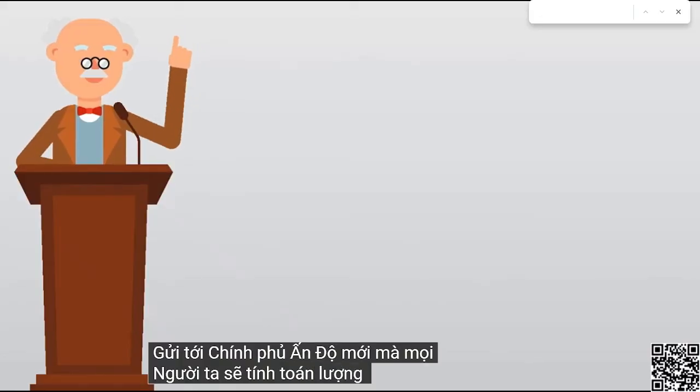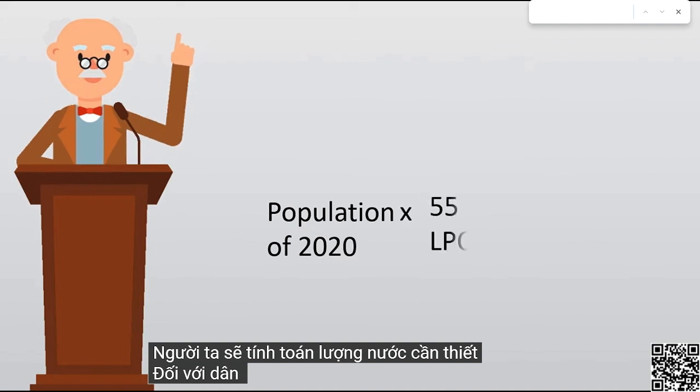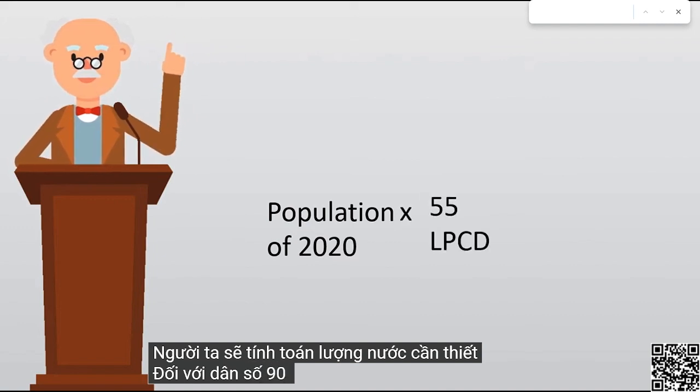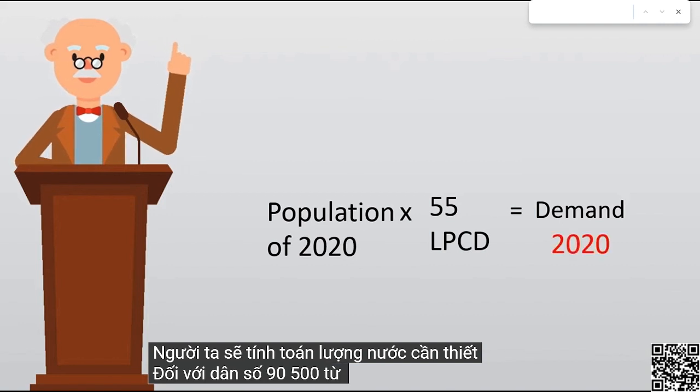So we will calculate how much water this village will need in a day. For that, we will multiply our population of the year 2020 with 55 LPCD. So this is our demand. But this demand we have got is for the year 2020.